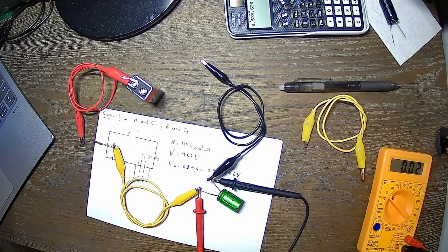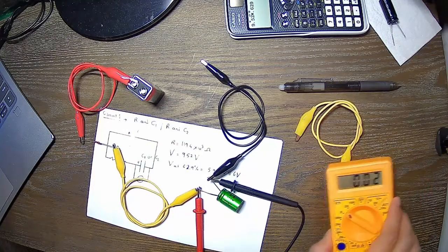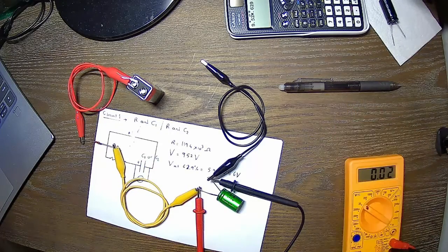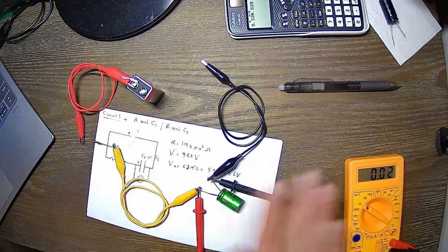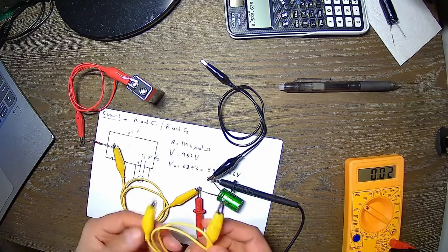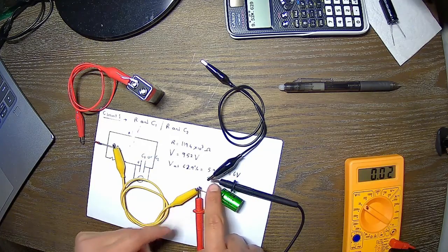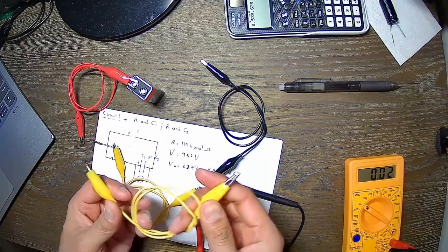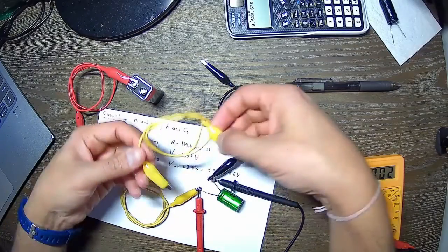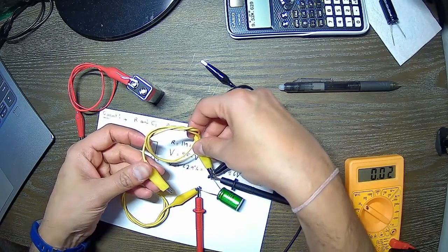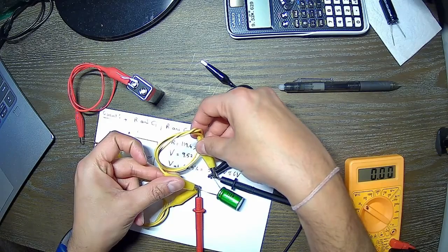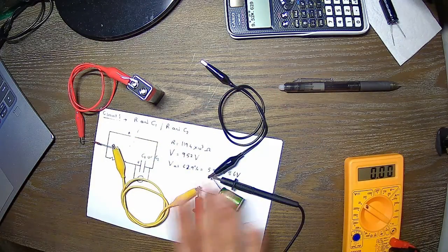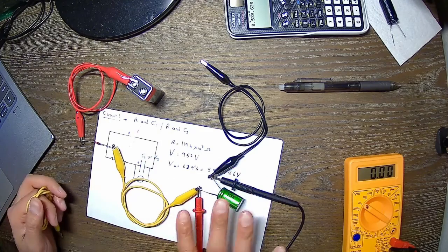Okay, so as you can see right now, it says there is almost no voltage, or 0.02 volts. So we always want to make sure that the capacitor is drained, so there is no charge separation. The way we can do that is by touching the two terminals, the two leads of the capacitor, together. To do that, I just use a wire. One end I touch here, the other end I touch here. And you can see on the multimeter it drops to 0 now. So the voltage is 0, and it's ready to be charged.